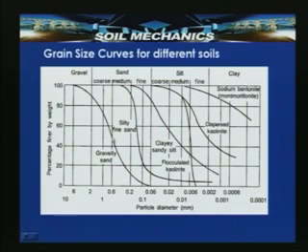A large amount of the particle size is more than 4.75 mm, which is gravel, followed by sand. So, the soil mass is composed of a certain percentage of gravel and predominantly sand, and then we call it a gravelly sand.